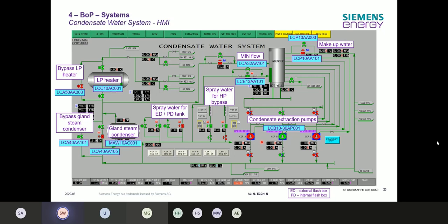So it should be on every centrifugal pump which needs the NPSH, there must be a protection for the pump. Otherwise, when the hot well level goes low to 0 or something, you will probably get damage on the pump. This is what I can say from my side.